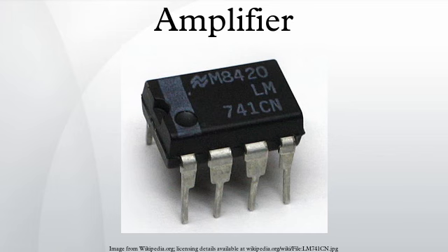Power amplifier. The term power amplifier is a relative term with respect to the amount of power delivered to the load and/or provided by the power supply circuit. In general, the power amplifier is the last amplifier or actual circuit in a signal chain and is the amplifier stage that requires attention to power efficiency. Efficiency considerations led to the various classes of power amplifier based on the biasing of the output transistors or tubes. See power amplifier classes.